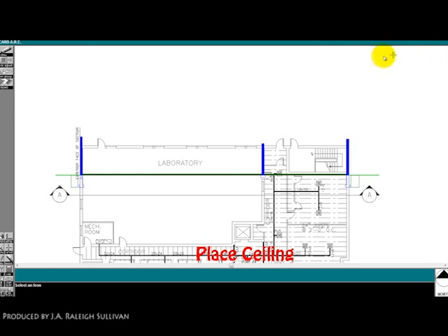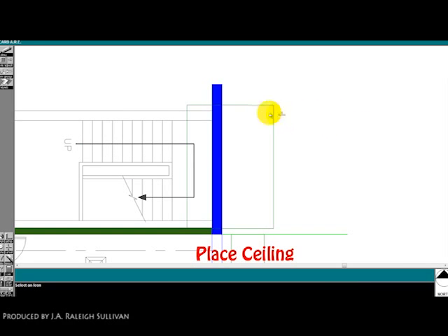We look in the program notes and we see that the first floor ceiling height is 8'4". So the first thing we'll do is draw a sketch rectangle at exactly 8'4". Kind of zoom in to make sure that we really did get it at 8'4" and not just a little bit off.